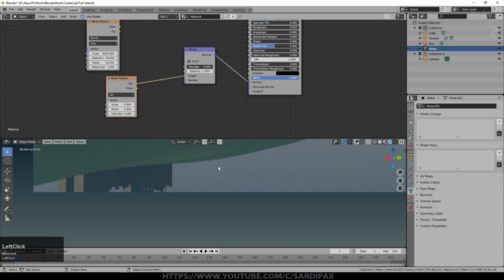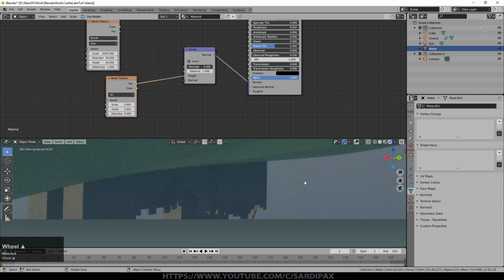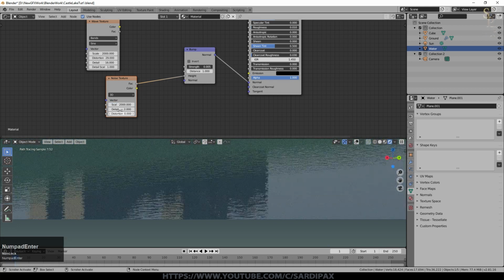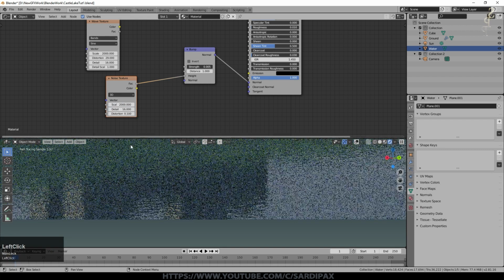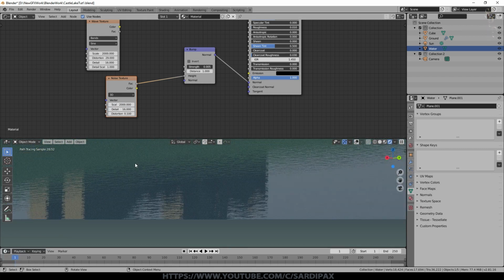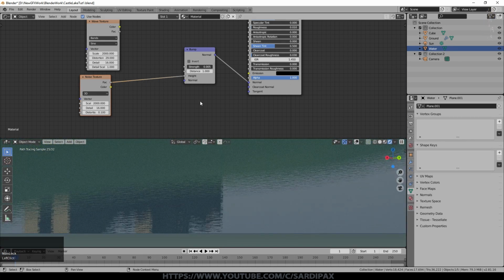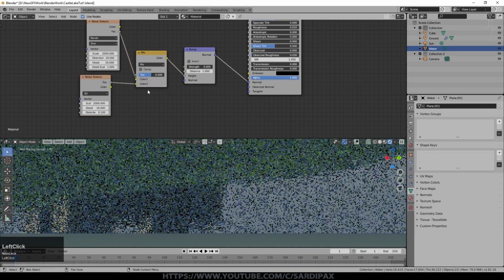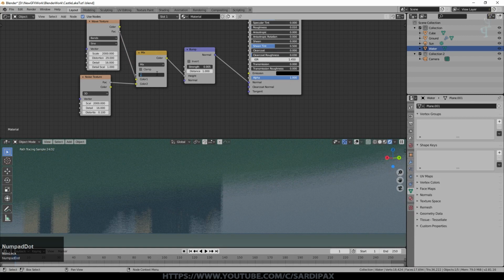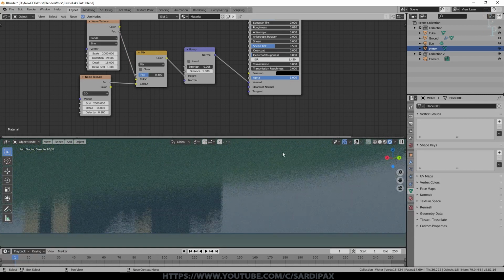The scale is very low right now, so it's not really showing up very much. Again, I used a scale of 2000. Detail is 16, and I put a very slight distortion of 0.1 on, so that adds curls almost to it. To be honest, either of those on their own are perfectly suitable. I often like to have waves as well as noise though, because you do tend to get, particularly in relatively still water, waves, ripples if you like, coming in from the surface or from anything that's disturbing the surface. So I also added a color mix node to mix those two effects together, and I had about 0.4 on that. So we've now got a combination of the waves and just random ripples.